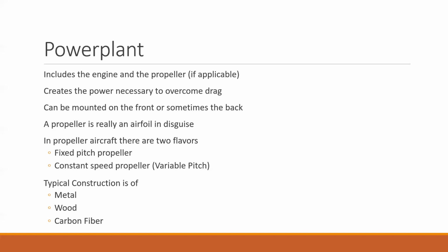And in between these two is usually where you keep it. So you adjust the propeller based on your flight angle or your flight airspeed. If you need more bite, you increase the bite, and if you need less, then you decrease it. And if you're flying a constant speed propeller aircraft, usually what you do is you fly based on a certain manifold pressure, and this manifold pressure correlates to the pitch of the propeller.